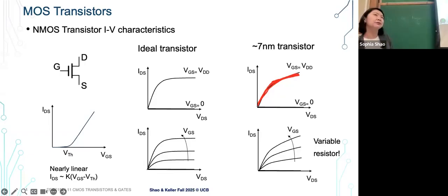So I don't think you folks are using 7 nanometer now. You folks are using Skywater 130 now. For older, we have been using ASAP7, which is the open source advanced technology node. It's actually a fake technology, useful for education, but not something you can actually fabricate.